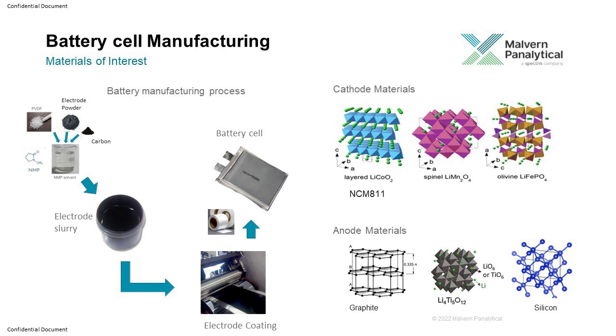For the anode materials, the commercial use material is the graphite, and in all commercial batteries that are available today, the graphite is the anode material. But people are trying to use other chemistries. Again, this lithium titanate, titanium oxide is used. Again, it makes the battery more safe, and it makes the battery to charge much faster and also have more lifetime.